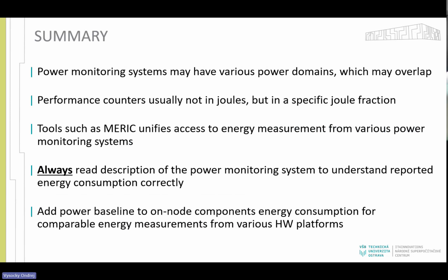So the last slide, the information I would like you to take from this part of the webinar: various power monitoring systems may have various power domains, and these may overlap. So you cannot take all the power domains and just make a sum of all the energy reported for each, because there may be too much, and also you should not pick just a single one, because there are usually several power domains on a single piece of hardware.